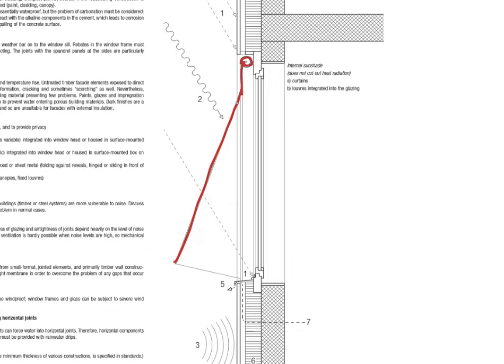So sometimes especially with office buildings that might not be always occupied, or there might not be a single person responsible for the safety of these elements, what happens is that they have a little sensor somewhere on the building, like a little wind wheel, that measures the wind speeds, and as soon as the wind crosses a certain threshold, these external shading devices will actually close, or they will roll up, just as a way to protect these elements so that they are not getting damaged through heavy winds. So that's one thing to keep in mind as well.